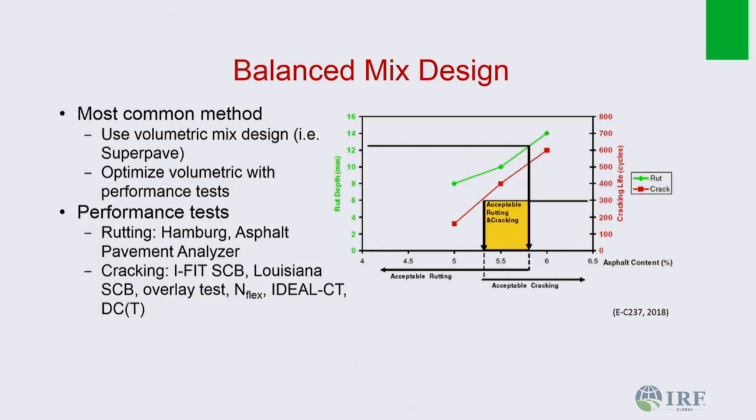All right, that's just by the way, but I think sometimes when you have countries with very high temperature, even if your mixes are good, you have a lot of rutting being an issue because of the temperature. If you are not using the Superpave, you don't have the right Superpave grade, then you will have that challenge. We can design for most of the cracks, especially the temperature-related cracks.